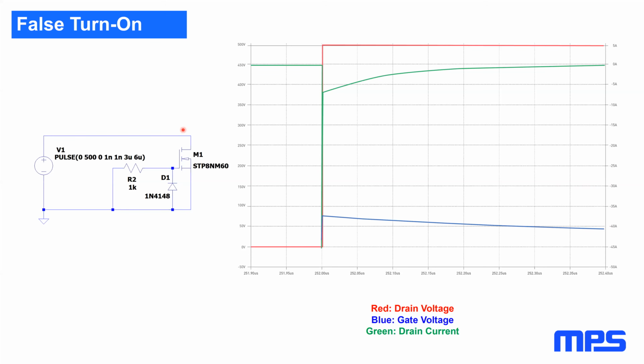So we're holding the gate at 0 volts through a fairly weak resistance, all right? So you would expect this MOSFET would just stay off. Now the problem is there's significant capacitance from the drain to the gate, between these 2 points. So if you apply a signal to the drain, even though the MOSFET's off, that gets coupled through that capacitance down to the gate.